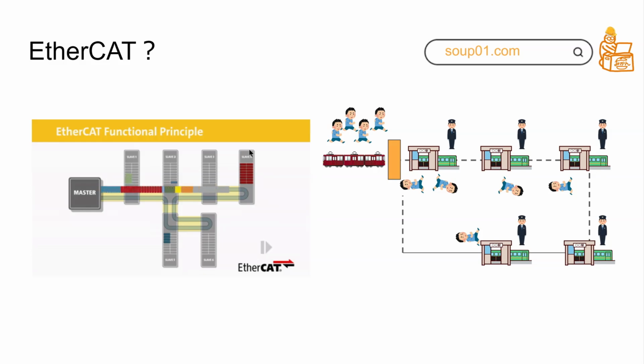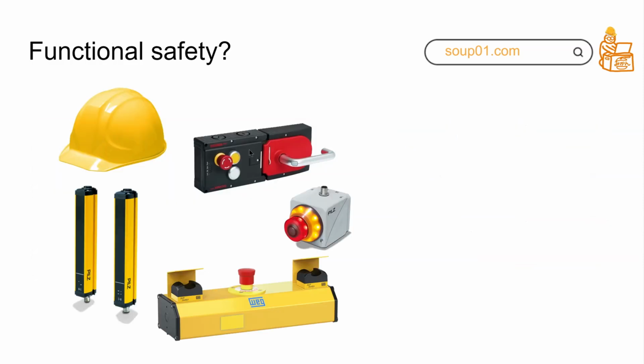Finally, when they go back to the EtherCAT master, it checks whether the counter is the same as expected or not. If not, that means this EtherCAT frame has a problem, and they will not use it. If yes, that means the EtherCAT frame has no problem, and they will use it. Very simple.